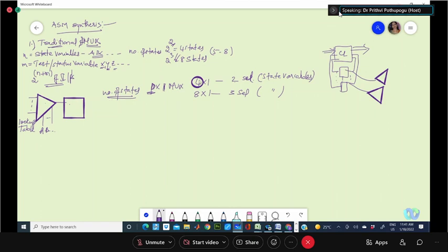So any number of states from 5 to 8, if we are taking 1, 2, 3, 4 and so on, 5 to 8 states, your 8:1 can handle. A 9-state system needs a 16:1 mux. In this, how many will be vacant? 9 will be used out of 16, and 7 more vacancies are there in your mux. Yes or no?